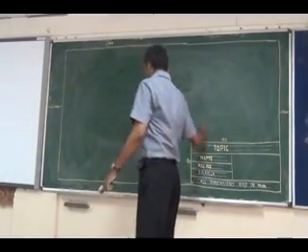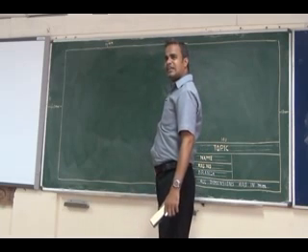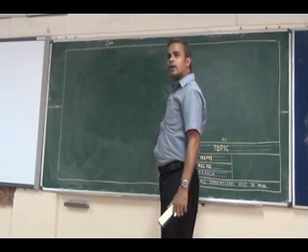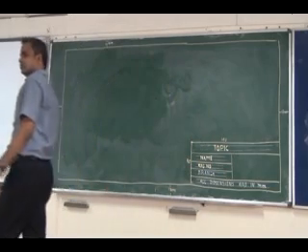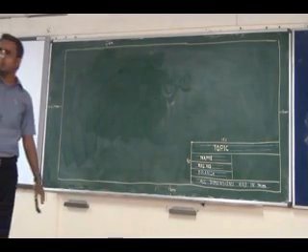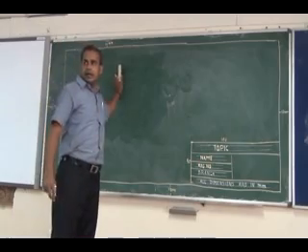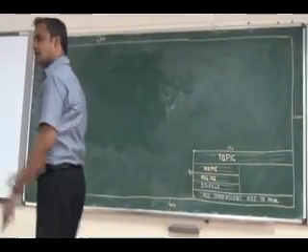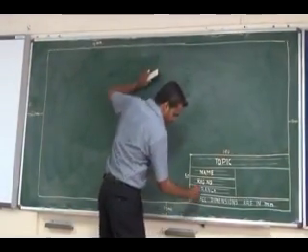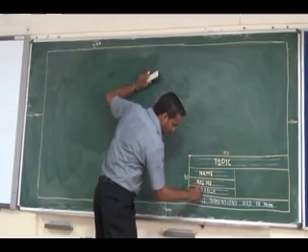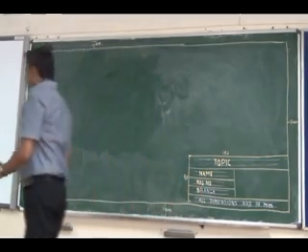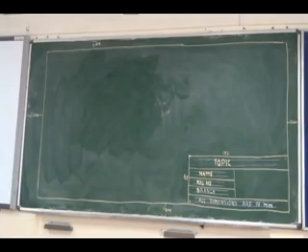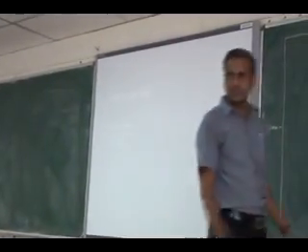Whatever you are going to write inside the drawing sheet should have a height of 5 mm, because we have only an A3 drawing sheet. Whatever text you are writing inside the drawing sheet should have a height of 5 mm. Keep a height of 5 mm. Then we do the title block. If you want, you can draw the symbol also.